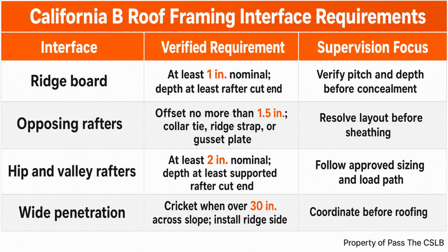I coordinate it before the roofing contractor arrives, because framing, sheathing, flashing, and roof covering all depend on that shape being present. A 42-inch chimney without the required cricket is not a flashing detail that can be casually solved at the end. A parapet roof changes the drainage problem because the perimeter can trap water. Primary roof drains handle the normal drainage path. The plumbing sizing rule in the supplied material uses a maximum rainfall rate of 1 1/2 inches per hour in designated areas as a baseline. The exact project design still comes from the applicable plans, rainfall data, and plumbing calculations.